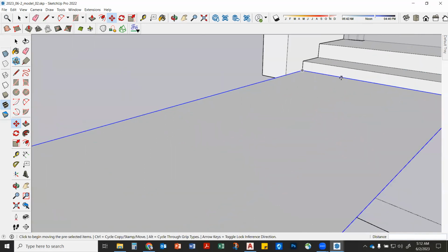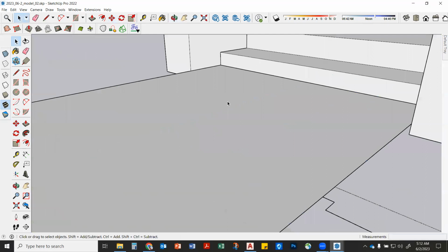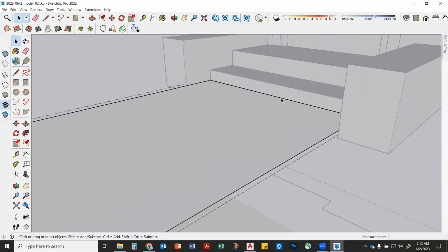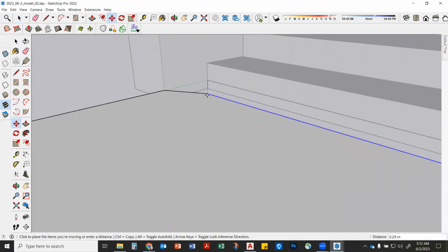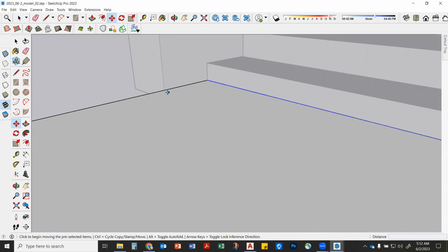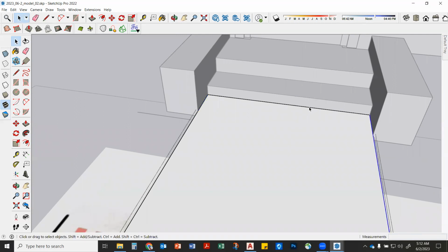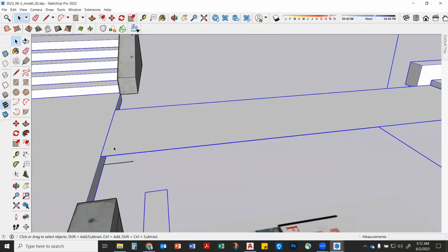So watch what we're gonna do. We're gonna come in here. We're gonna double click. I made this walk into a group just so it wouldn't stick to all my other stuff. So I would double click inside that group, select that edge, M for move, and then I'm just gonna click on the edge over here, and then whoa, hold on now. Oh, there's a break right there. So watch this. We do view. Oh yeah, hidden geometry. So evidently this line's already broken. So let's not do that. Let's move the whole thing down and then change this end.